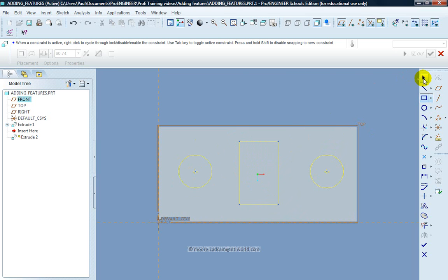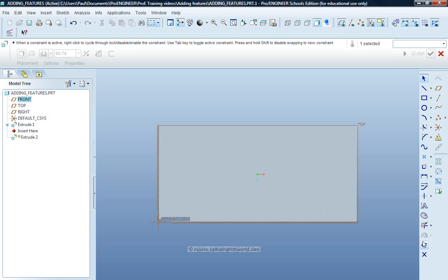If I click on the Select Items arrow at the top, you can now see I've got the dimensions for these, so I can set the dimension at 50, for example. Set the length. That now becomes a strong dimension, so it's less easy to change that length of that particular part. And I could do the same with the circles. If I change the circle, say to 45, you'll see that both circles will change because they've got the same radius. I'm happy with that. I'll then just click on Done.